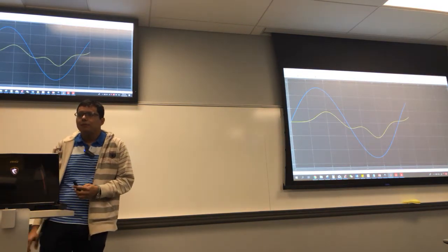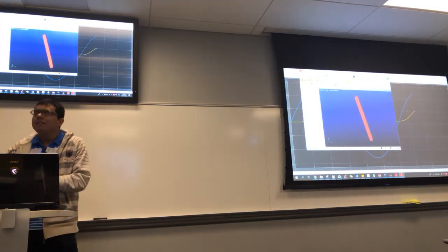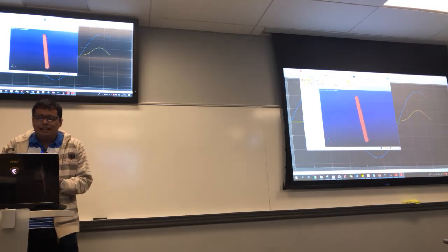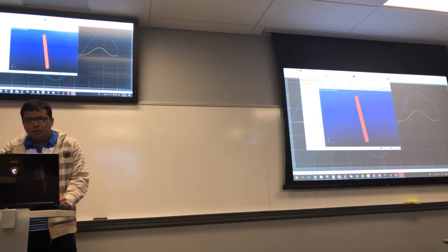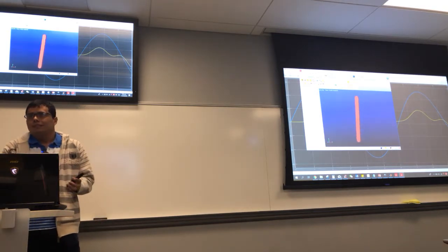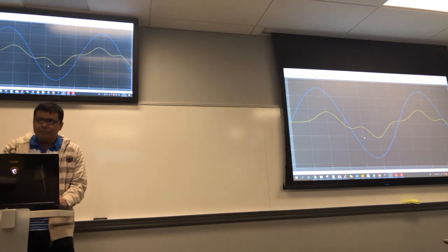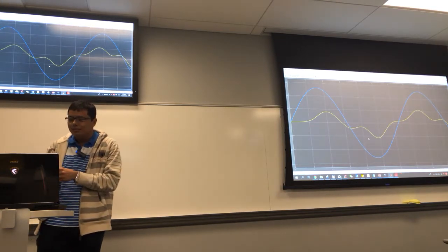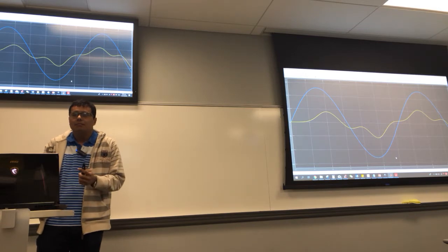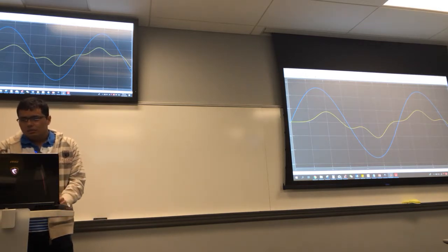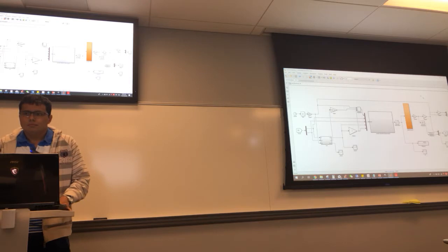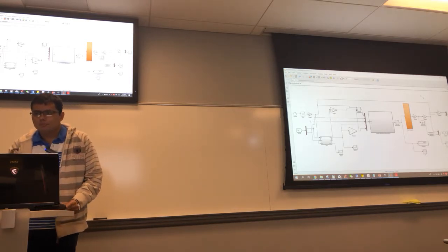It was a preliminary test that I'm performing, but the idea of this test is, if we have the model, in this case a real model of the system using MSC Adams, it's like having the pendulum in real life, but in the computer. So what happens with those algorithms that work for adaptive performance? The algorithm, the yellow line, tries, but for sure in this system I need more neurons, because it's the real system. It has friction, and uncertainties that I don't know at this moment. I think this gives you enough flavor of neural network control and nonlinear rigorous stability analysis. So I hope you enjoyed it.